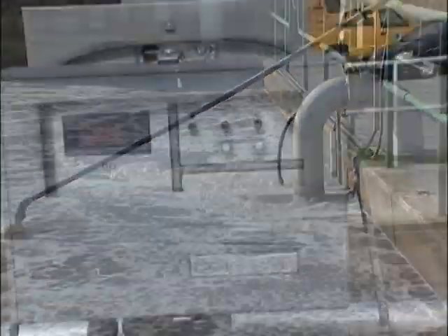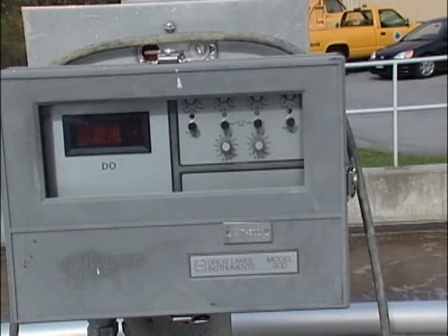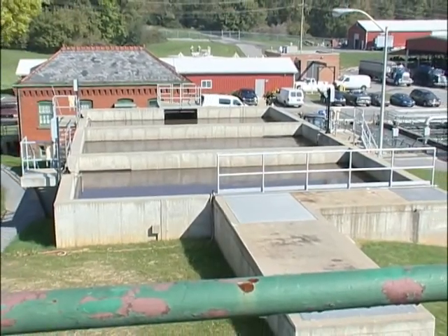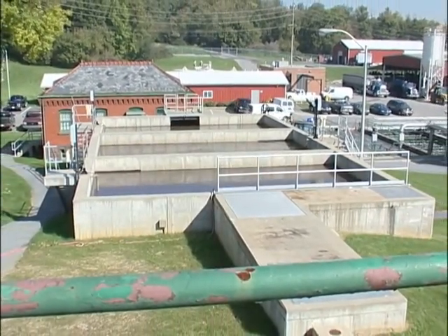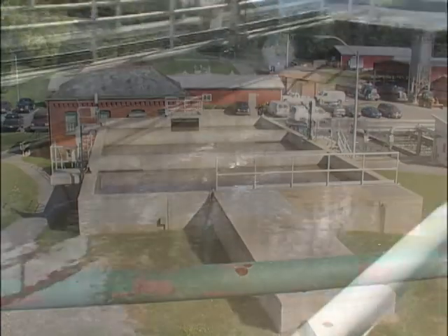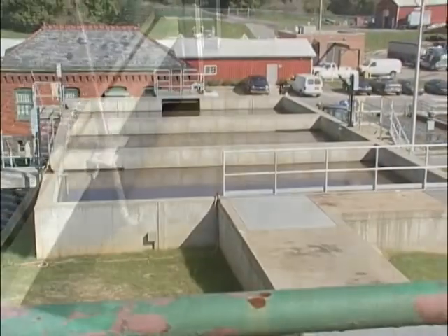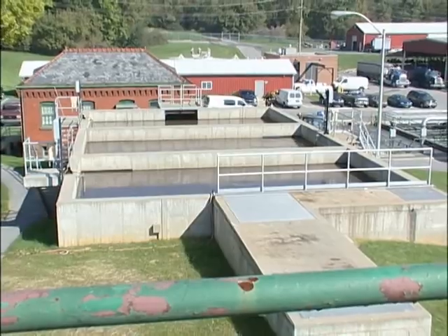The efficiency of upstream treatment units is critical and must be monitored. In the case of multi-staged biological processes, CBOD should be reduced prior to nitrification. Typically, facilities that have an upfront anoxic zone experience a significant reduction in CBOD through the anoxic process.